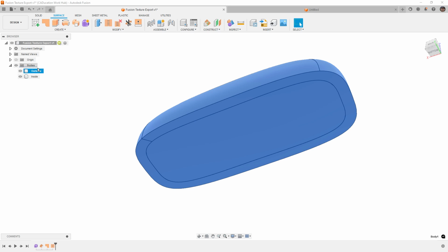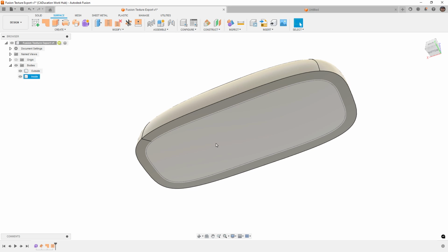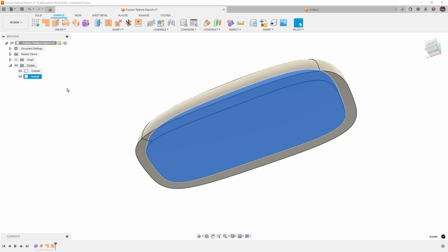Now, the reason this is important is because we have the ability to do Boolean operations in Blender where we can subtract one mesh body from another. So having the inside, or the smooth version that we want, even if we end up having to scale it up a little bit, that we can use to cut away the texture we add, is going to allow us to add those in the modifier stack after we add that displace modifier.